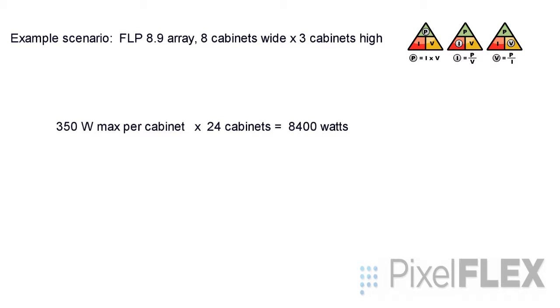It is recommended to overrate your power requirement. As in real-world scenarios, you will have some loss on your cables, as well as taking into account general overhead to avoid fully tasking your power source. We recommend at minimum a 15% overrating, so in this example, we will use 9,660 watts as our power load.